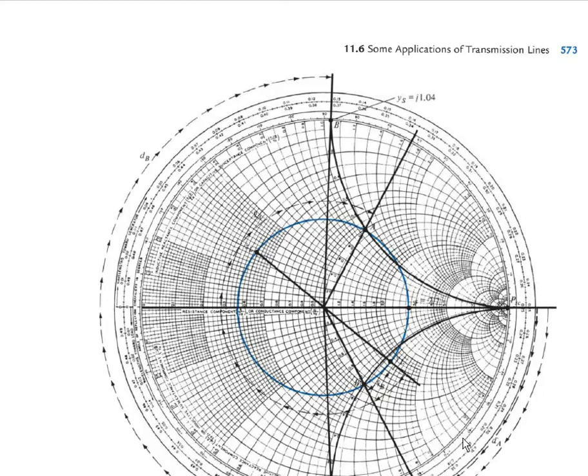So here from this second circle we will get the angle easily. From this angle, first you measure this angle directly, then convert that angle to lambda terms. For that, multiply and divide a lambda term with this obtained angle. The multiplied lambda we keep as itself. The divided lambda we convert as 720 degrees, because 1 lambda is 720 degrees in this Smith chart.